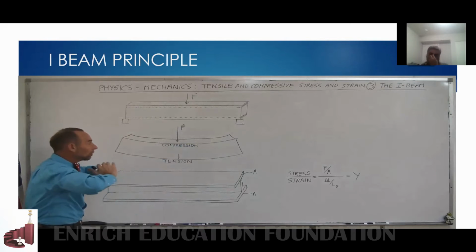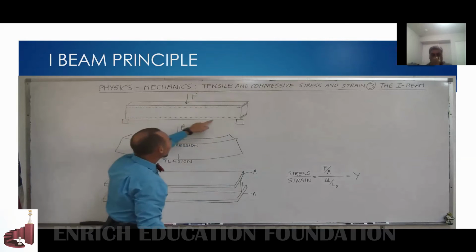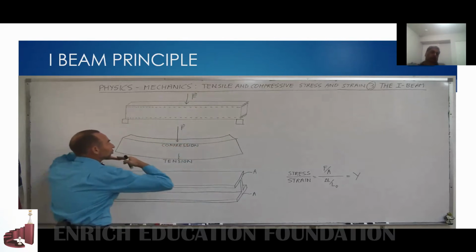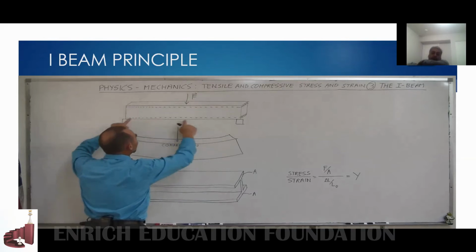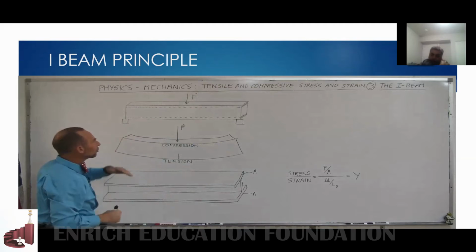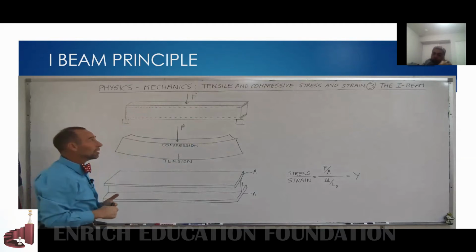The most force is applied to the beam, pushing the molecules together. And the bottom end of the beam is going to be under the most tension. Because of the sag of the beam, the molecules are going to be pulled apart the most at the very bottom of the beam. So those are the two portions of the beam that are the most important, and the portion in the middle is not nearly as important for the strength of the beam.